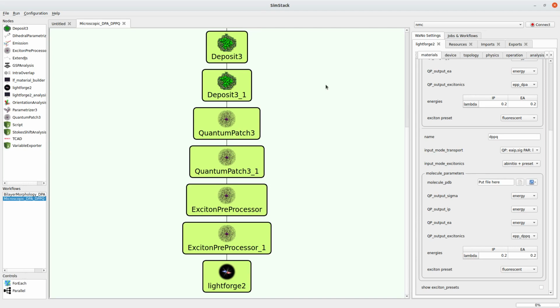This OLED is designed so that excitons will be generated at the interface between DPPQ and DPA, and light generation and quenching should also happen near that interface. To confine excitons to these layers, and to prevent leakage currents, we will add also an electron and a hole blocking layer adjacent to these two materials.